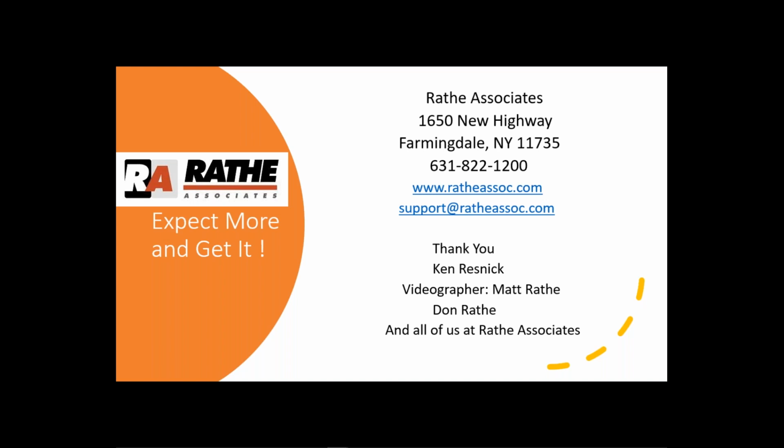Personally, and here at Rath, the other tech support guys, we take our analyzers in from the car at night and we bring them back to the car in the morning. You'll get used to doing it. It's going to sit by your front door, and it's the first thing you grab on your way out. So please do not leave your combustion analyzers in your vehicle overnight, especially here locally, Long Island, New York, Northeast. Such tremendous changes in humidity levels that can create issues with that analyzer. But great question.